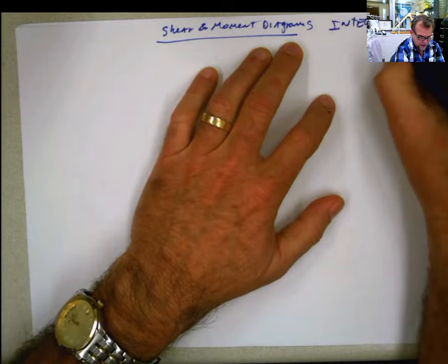So this is going to be 0, and my shear is going to be constant. Now that constant is a boundary condition. What is that boundary condition? If we are looking at shear and we are looking at the span AC, it is the value of the shear at the point A, and this is read from the diagram. So in other words, you come to the diagram and you read the value at A.